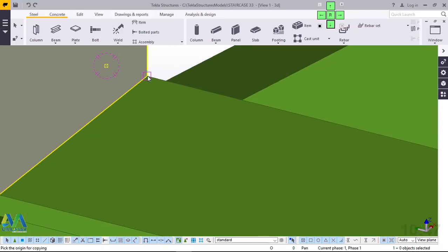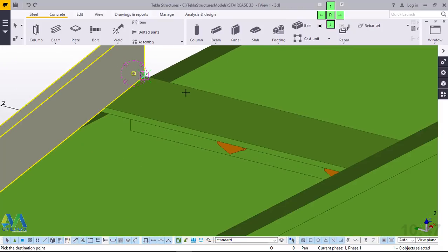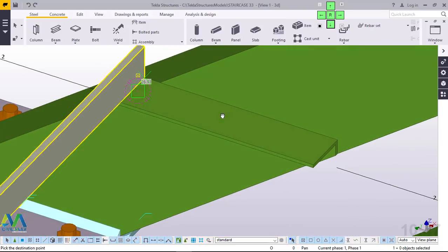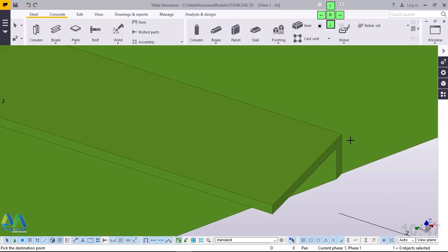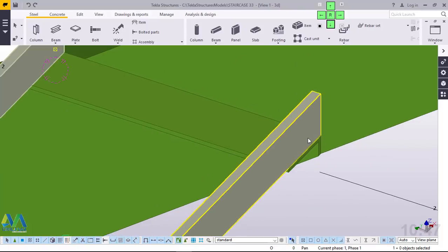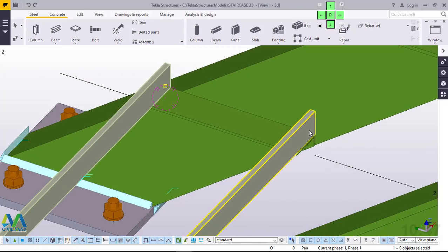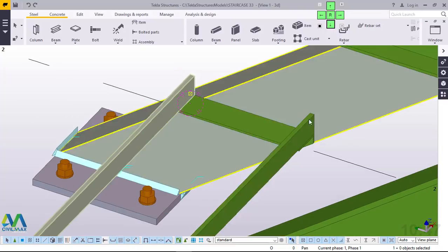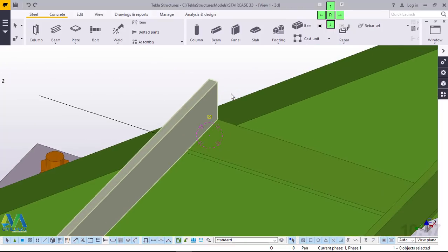then we'll snap right at the bottom of that bar, then we'll turn this to a position we can see clearly, then bring it close to this spot right here. Perfect. Right click and exit. Exit means you right click, click interrupt. Interrupt will wind up the command action. Now I'll come to beam right here again.